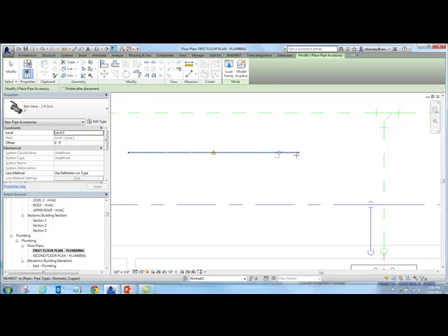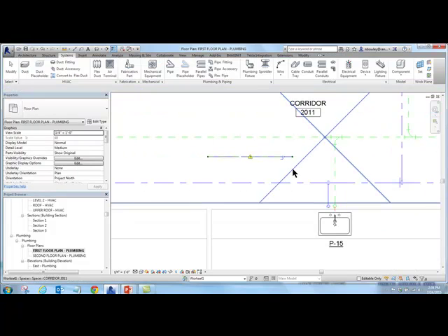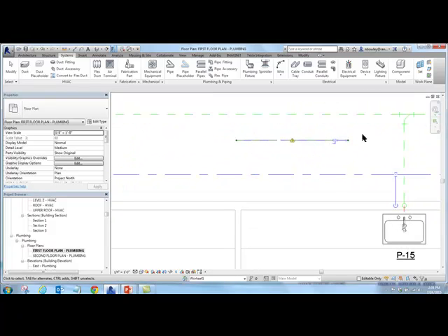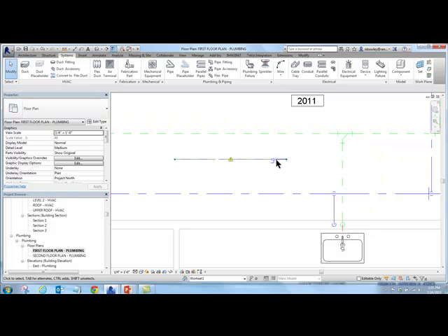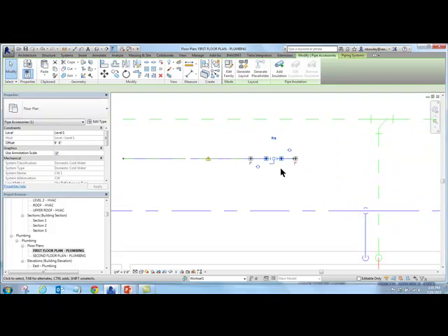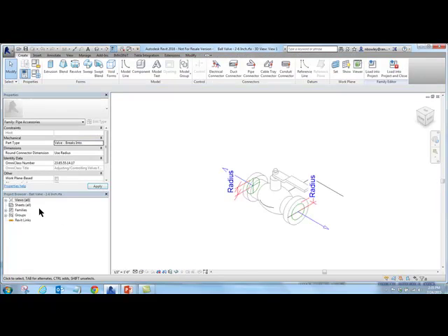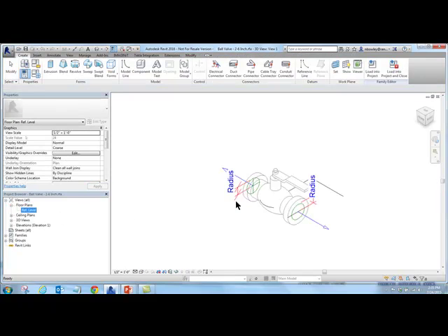All right. So the ball valve comes in really, really tiny. So the workaround for turning off annotation scales so you see the fittings at the true size and yet having your valves come in the correct size is to open those up and turn them into generic annotations. So you end up coming in here and go to the top view.